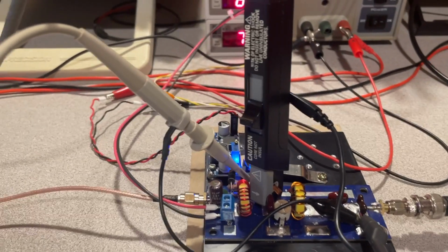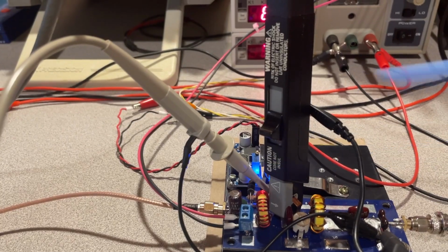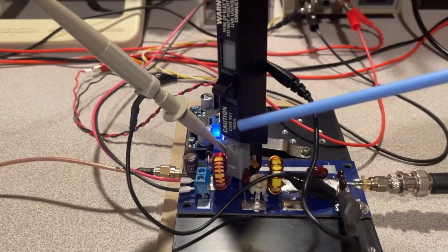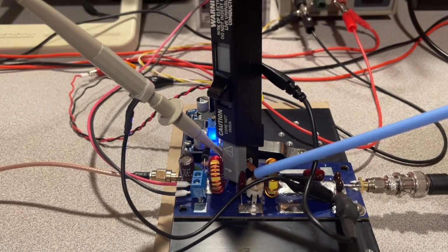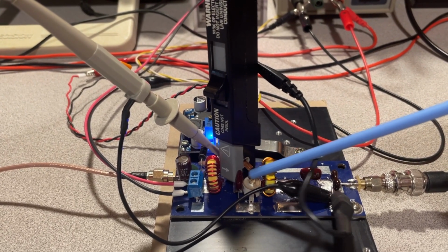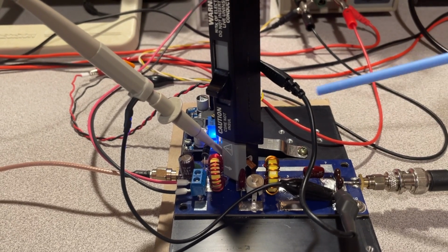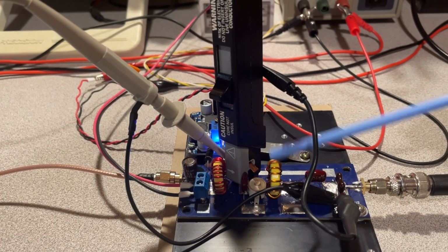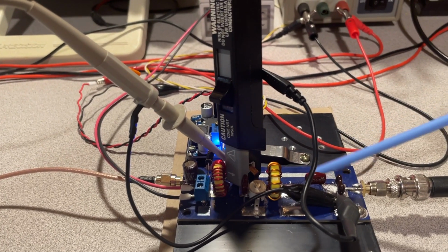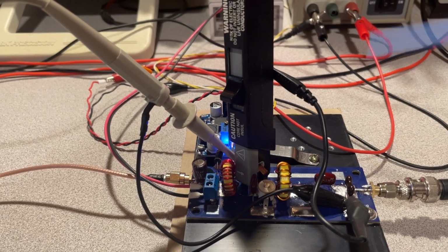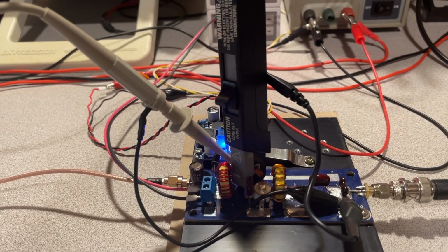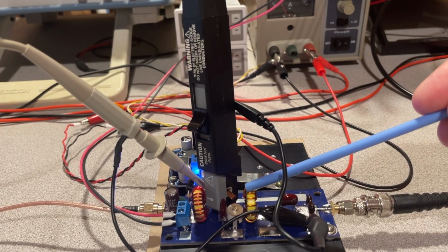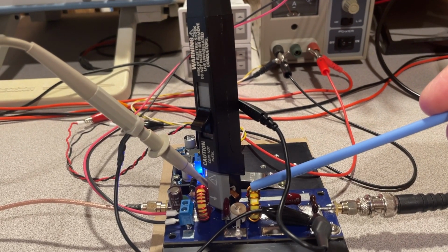And again, let me just describe, we've got for the Class C amplifier, the RF choke here, and we have a shunt capacitor. I put in a trimmer so I could optimize that value, and then we have basically the load network, which is LX, and the two capacitors that are used in the resonator circuit and also the matching circuit. So all I did here was combine the inductor values into a single inductor.